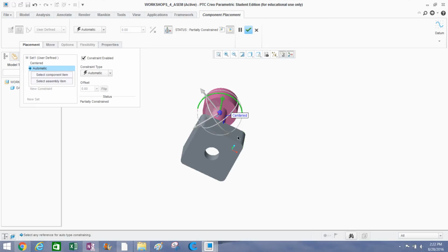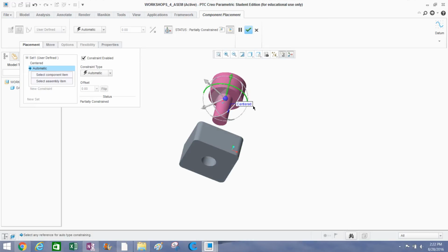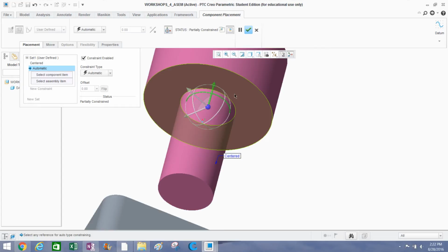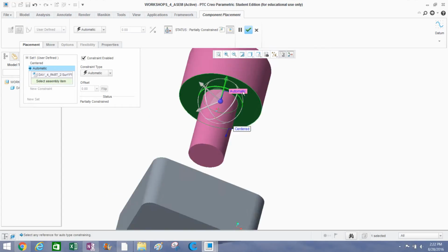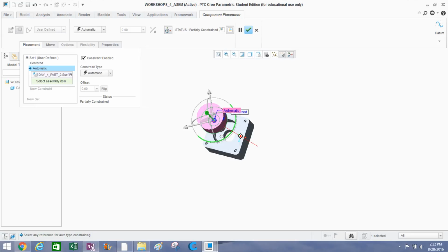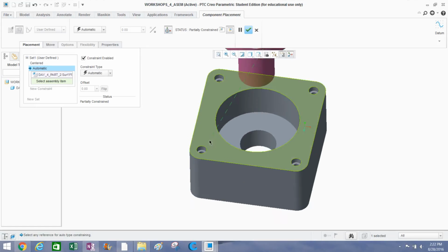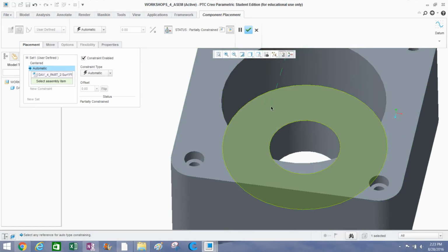And we're going to go ahead and click the two surfaces we'd like to be coincident. So you're going to start with the item, which is your part you're working with. In our case, we're going to choose this flat surface. Left click it, and then come down, look at your block. You're going to want to pick this other flat surface.